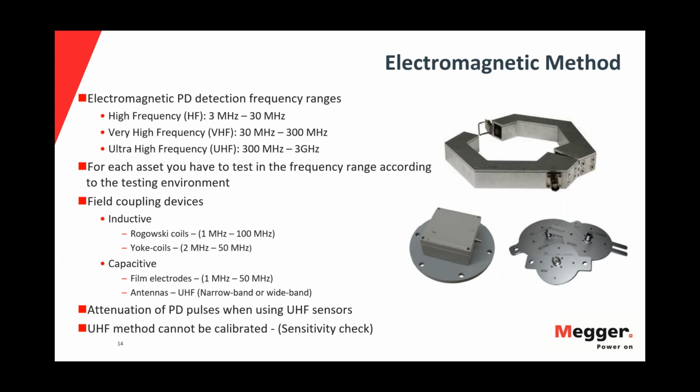For example, liquid insulation in a power transformer has a pulse rise time in nanoseconds, which equates to 350 megahertz. As the pulse travels through the transformer to the measured area, that is reduced to around 40 to 50 megahertz at the measurement area.